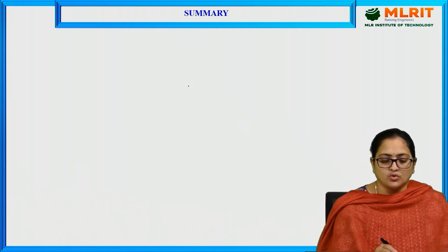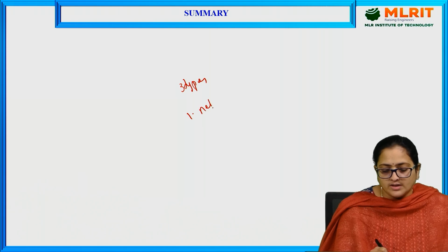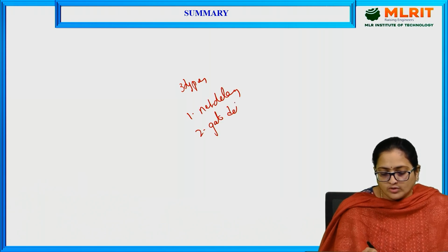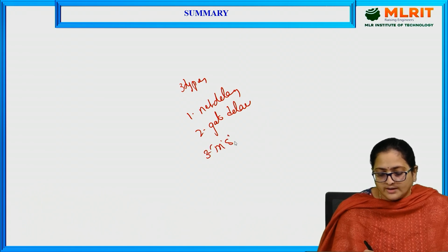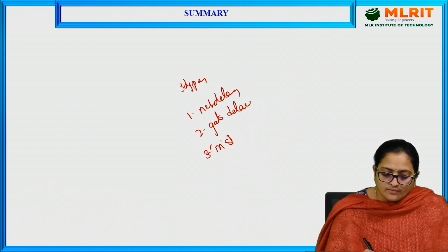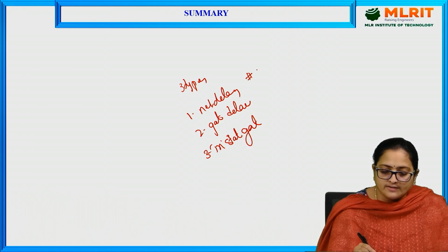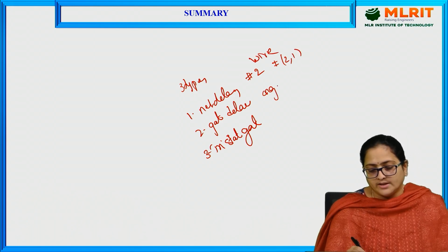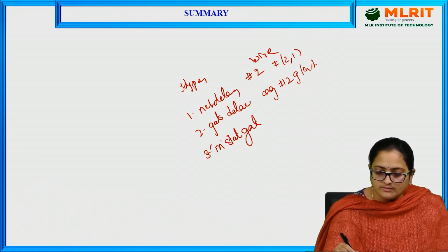Here in this video we have discussed 3 types of delays. The first one is net delay, the second one is gate delays, how to implement the delay in primitives. The third one is tri-state gate delays. In net delay, you can simply give the delays for the wire, whereas in gate delays, you can give delay between the gates like this.